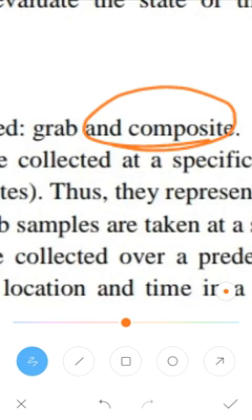Some composite samples are collected by using continuous constant sample pumping, or by mixing equal water volumes collected at regular time intervals. Flow-proportional composites are collected by continuous pumping at a rate proportional to the flow, or by mixing equal volumes of water collected at time intervals inversely proportional to the volume of flow, or by mixing volumes proportional to the flow collected at regular intervals.